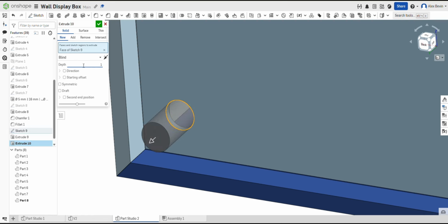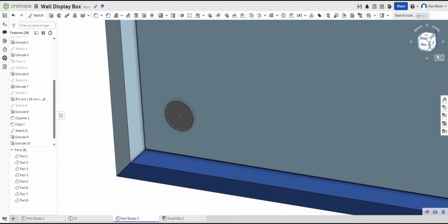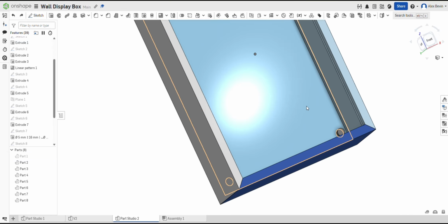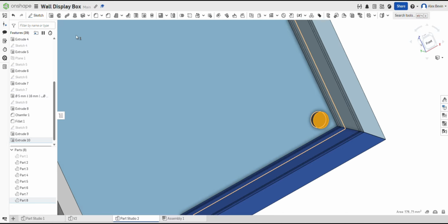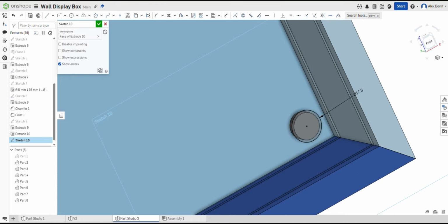Step 3. Model the left-hand shaft only, new part. We're only modeling the left-hand locking mechanism in this example. So I'll extrude the left hole profile again, but this time as a new part. Now watch the directions. From the outside face of the acrylic, I extrude 1 millimeter towards the outside and 11.1 millimeters towards the inside. That places the shaft correctly through the acrylic. Press OK.